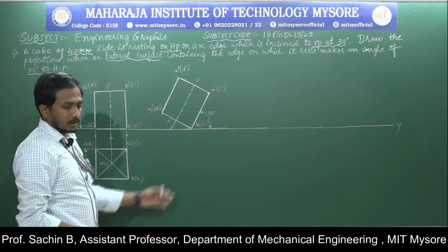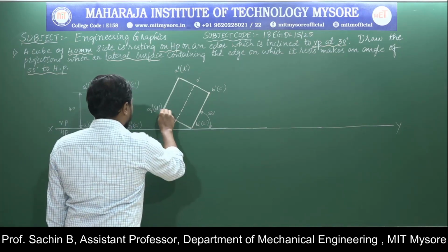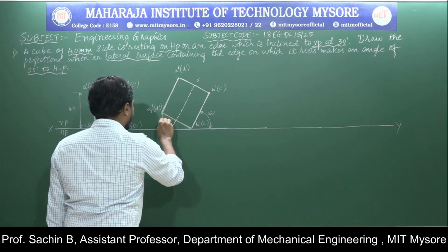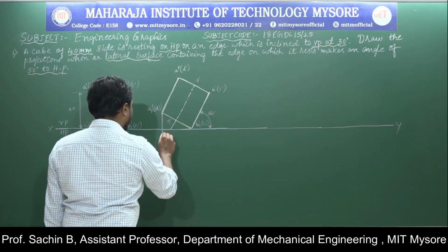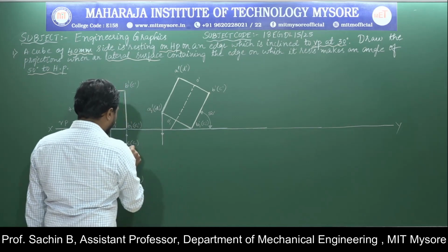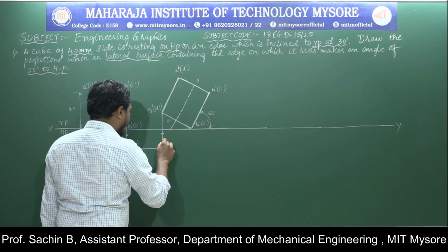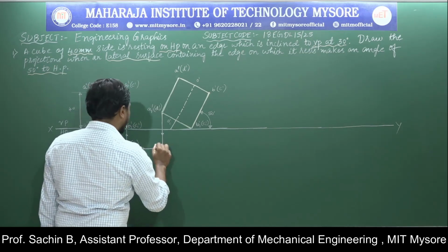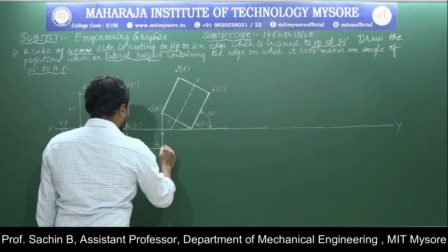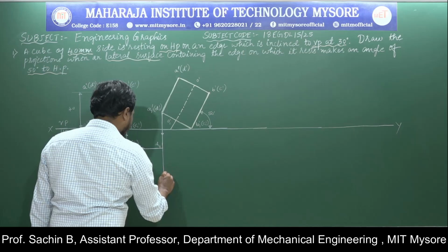Now to get this top view in the second position, I will draw the projection line from all the corners. From A1 dash to D1 dash, I am drawing the projection line from the top with filled arrows, which should be written to show the representation of the projection line. This is D1 point. Again I will extend that line with a thin line.